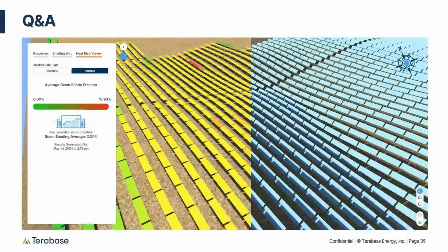In PlantPredict, you have your design, your 3D shade scene, and your blocks and arrays, and they're completely separate. So we take the bifacial gain from the orientations section of the model, and we just use the NREL bifacial view factors model.